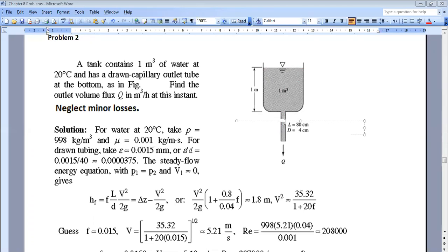But what I mean is: when do we assume this and not work with the upper part, and when do we try to solve it and use the relation? For example, if they give you a tube of 6 centimeters and another tube of 4 centimeters, then you cannot neglect it, because the velocity will be smaller but not by much. In this case, if the diameters are not very far from each other, they are nearly close, so you must divide into 2 parts. Here you can calculate d and compare the two d's. If there is a big difference, you can say I will neglect it. If not, you should divide into 2 parts as here.